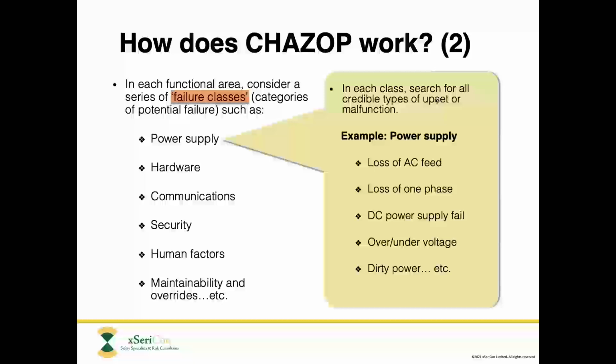And the functional areas that I will normally refer to are, most importantly and firstly, the main process control system, DCS or BPCS. The SIS, which is Safety Instrumented System or Emergency Shutdown System, will be another functional area to look at. Panels, local panels, any panel that has got control functions within it. If it's just indicators, then we probably don't really need to look at it in detail.